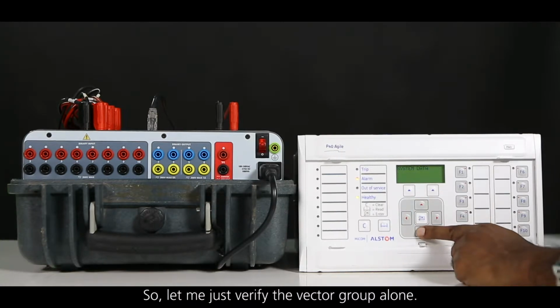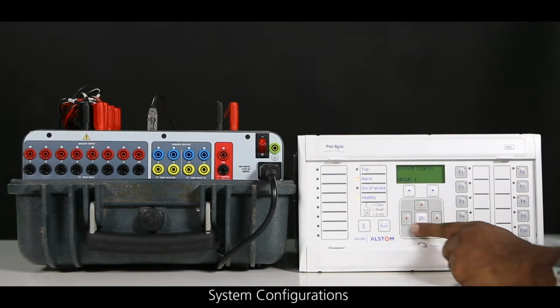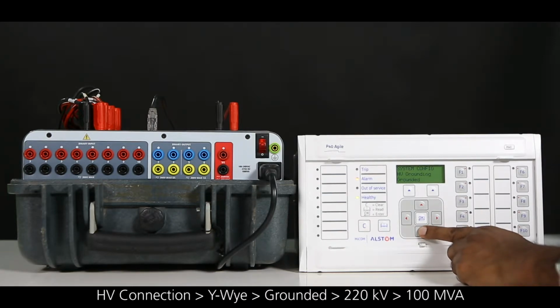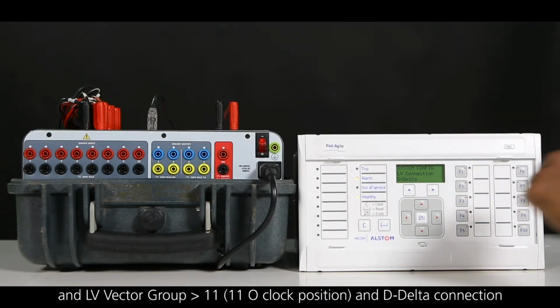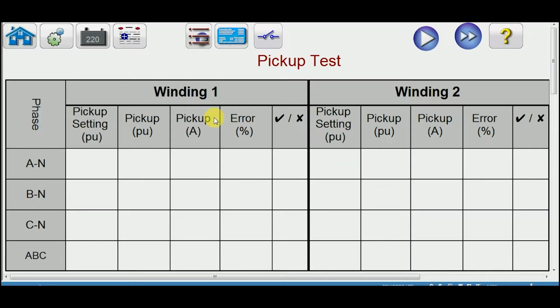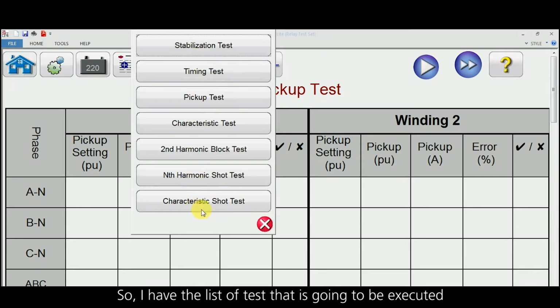Let me just verify the vector group alone. System configurations. HV is Y connection grounded, 220 kV, 100 MVA, and LV is 11 o'clock position and delta connection. Once this is done, let me put a tick mark. So I have the list of tests that is going to be executed.